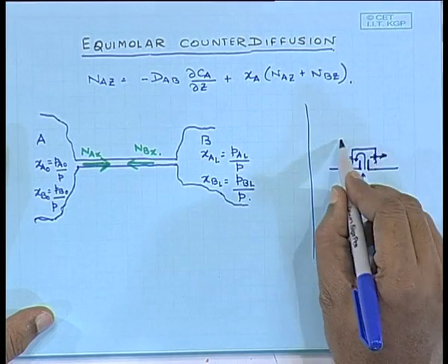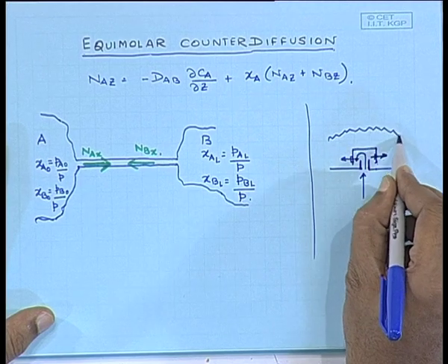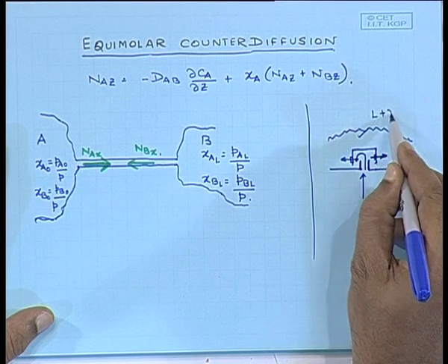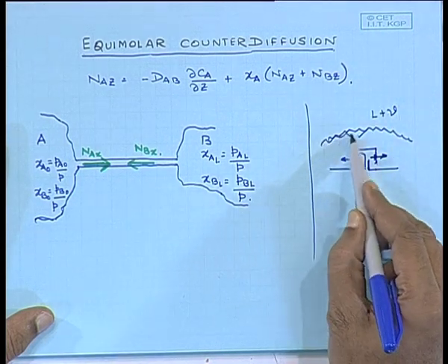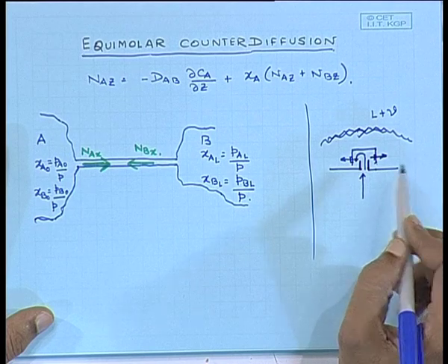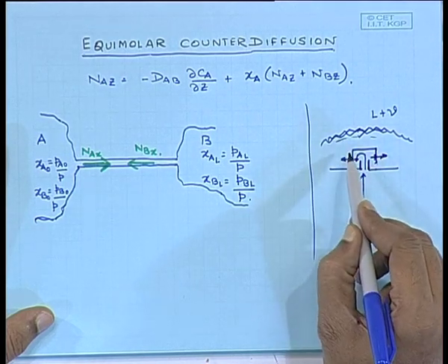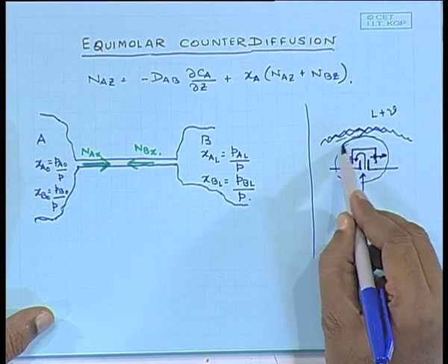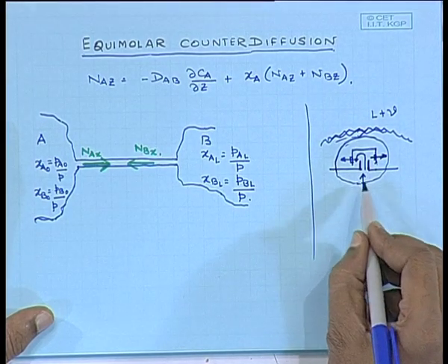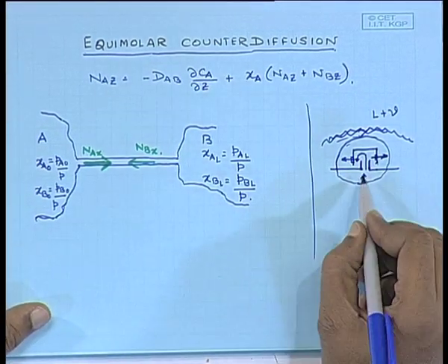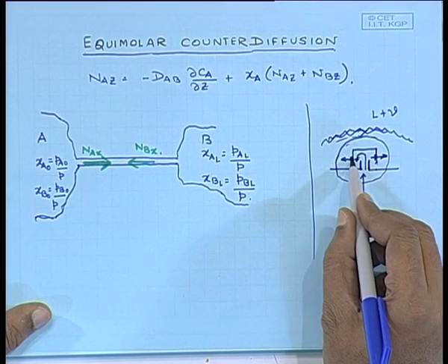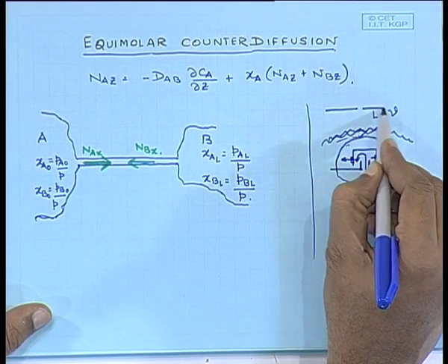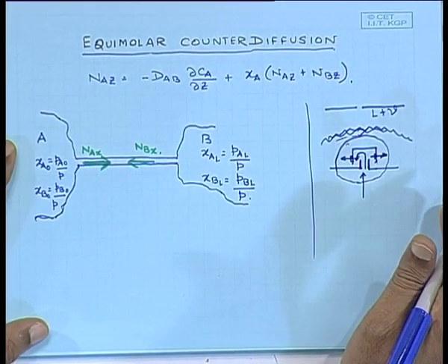but the vapor will come in this direction and the liquid forms an agitated mass over each bubble. So, this is a mixture of liquid and vapor. It is almost like a foamy solution. The more agitation that you can provide, the better your mass transfer would be. So, the commonest type of contacting device is known as a bubble cap. Gas flows in, comes out of the slot, mixes with the liquid and goes to the next tray with identical situation, with identical construction.